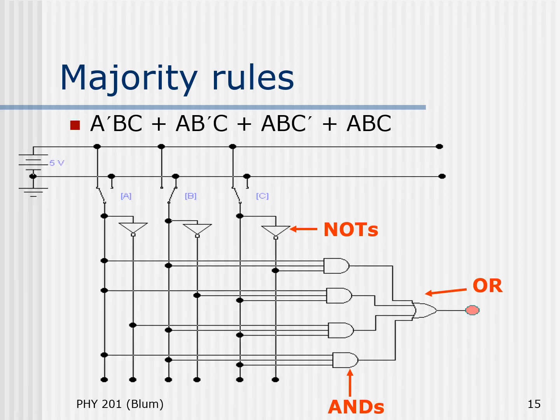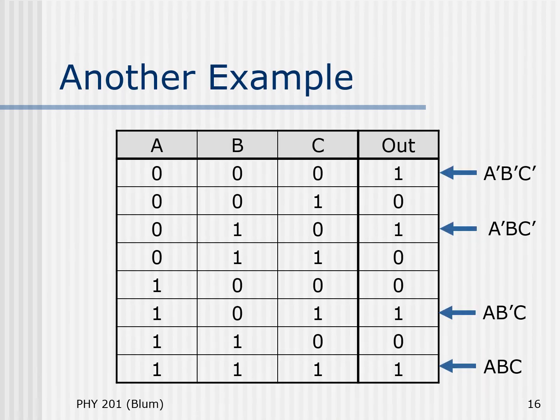So in this picture here, we have not changed any of the wiring. We've only changed the values of the switches. So now we can see that A is connected high, B is connected low, and C is connected high. So two of the inputs are high. And again, we were realizing majority rule. So 2 high should give us a high. And we see that the probe of the output over there on the right is filled in, is lit, is high, is true. So again, it's important that you understand that majority rules with just an example.